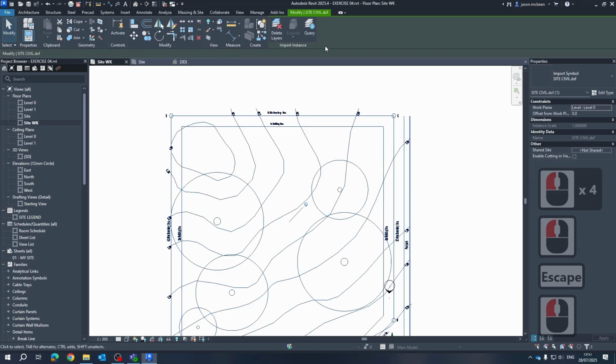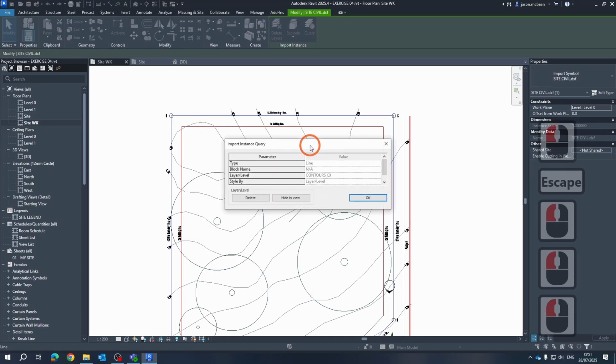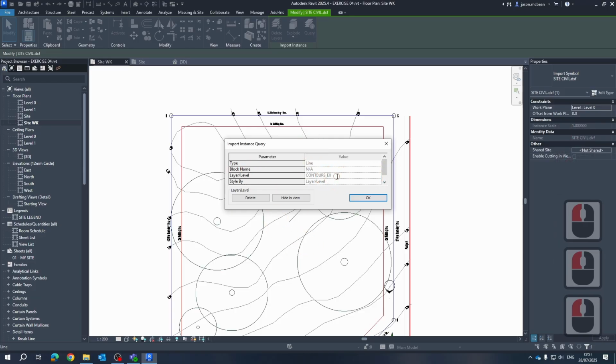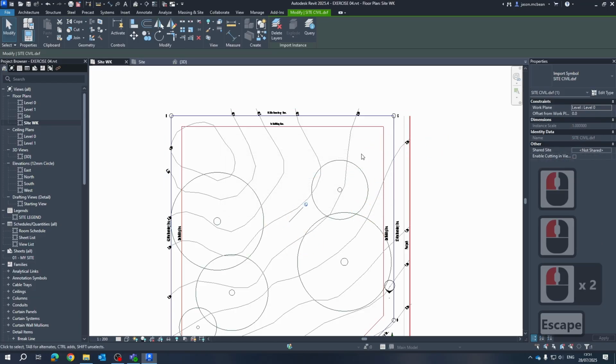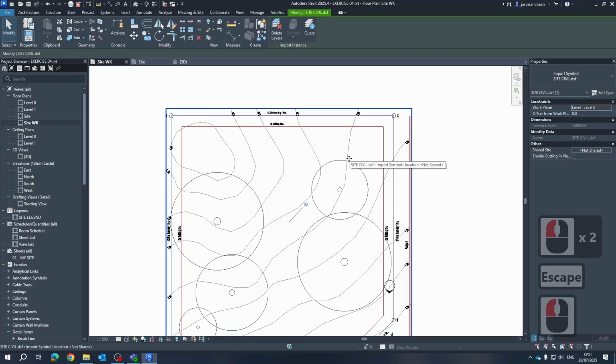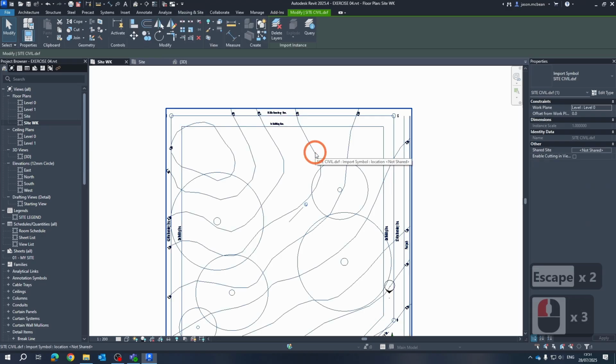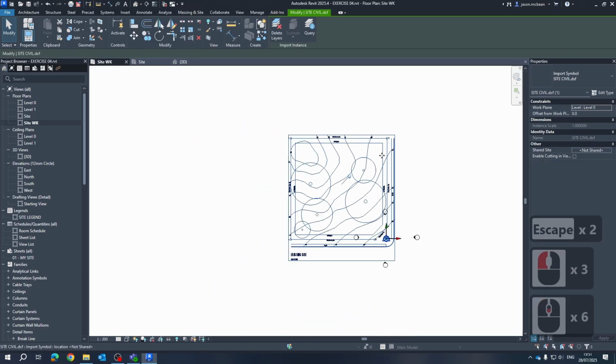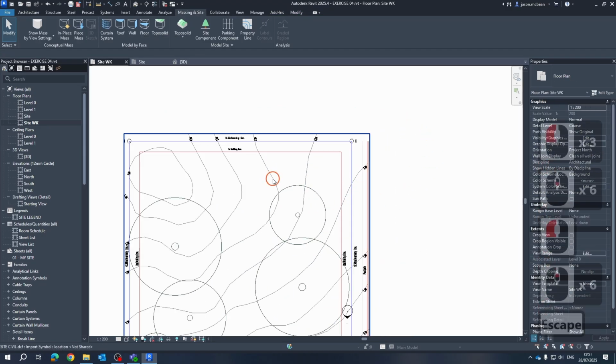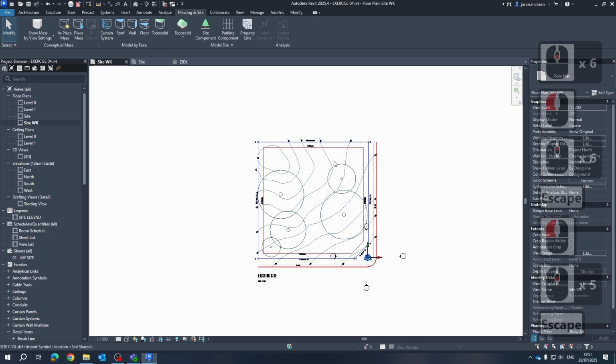But you can use the query tool and select certain layers within the drawing and you can see the layer name. So maybe before you extract the information from other sources, just make sure that you know what layer the contours are on. Okay, so that's very important. When you're exporting stuff from QGIS, just make sure that you've named things correctly so you know what everything is.